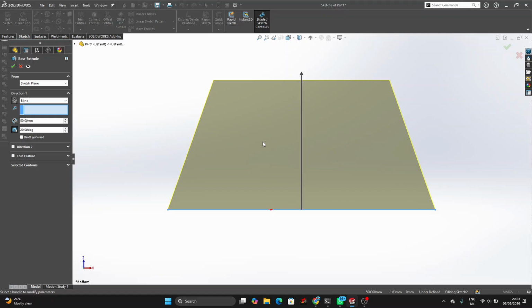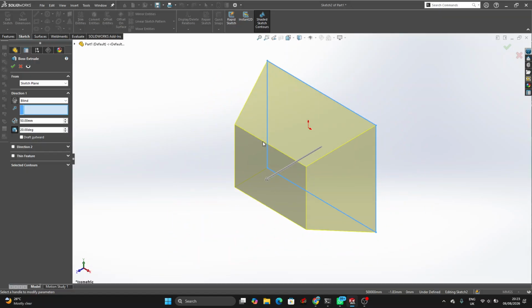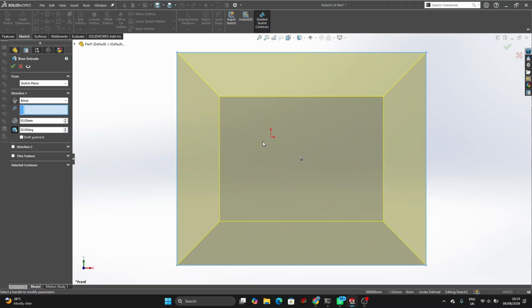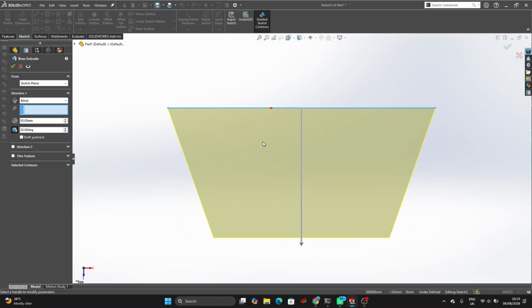Control, that means you click on your Control key and click on 7. That one is isometric view. That one is you viewing it in 3D. And Control 8 is like an alternate view. Maybe you are in front view now, Control 1. Instead of clicking on Control 2 for back view, you can click on Control 8. It will go in the reverse direction to take it to back view. So we are on Control 5 now, which is top view.